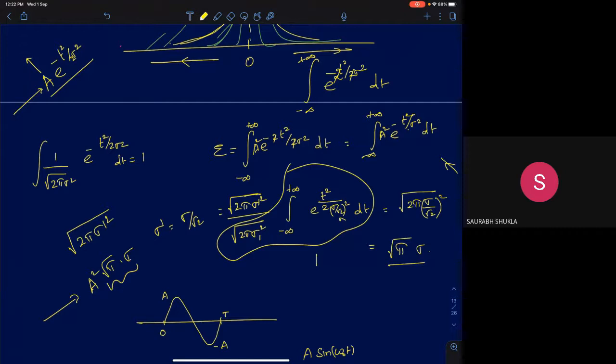Okay, so far what I've discussed is the definition of energy of a signal. Then I took some standard 2 to 3 signals, a pulse, a Gaussian function, and also a Sinc function. I haven't computed its energy, but I've just introduced you to a function that looks like a Sinc function. Why did I discuss Sinc functions? Because when we talk about transmitting signals, there is an interesting signal called raised cosine filter, which looks like a Sinc, but a modified version of a Sinc.